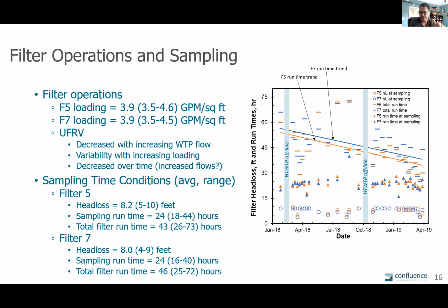And the circles at the bottom are the head loss of the two filters that we sampled, which was roughly 8 feet each time we sampled. We tried to be consistent across the year to monitor a consistent period in the filters' operation.